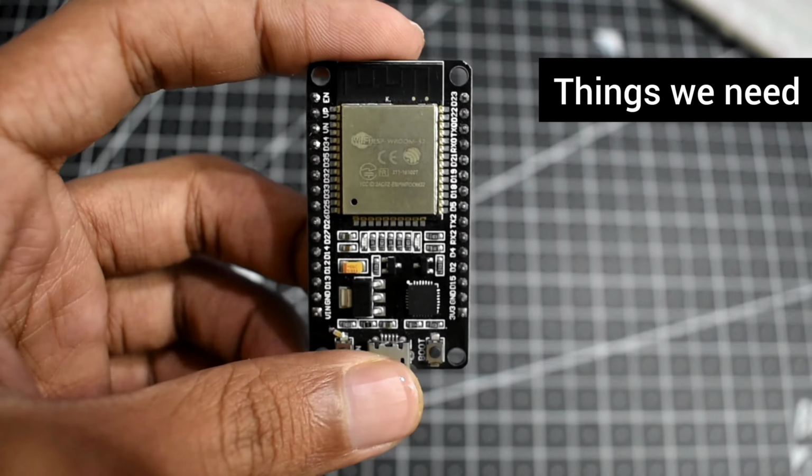So the DHT11 sensor will have the data transmission, and the data will be transmitted from the data pin, and it will be given to GPIO 4 or D4 pin on the ESP32. So let's connect the ground of the DHT11 to the ground of the ESP32. The data pin will go to D4, and then the VCC pin will go to 3.3 volt. Now 3.3 volt is more than sufficient for the DHT11 sensor. If you have any other sensor, please consider using an external power supply.